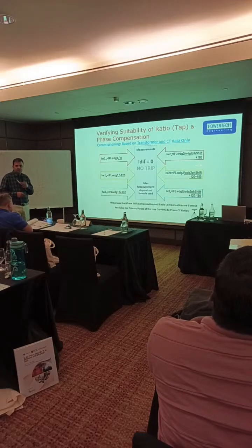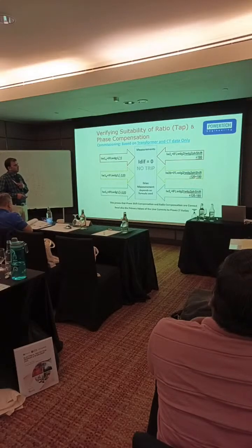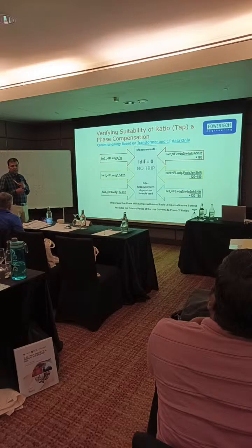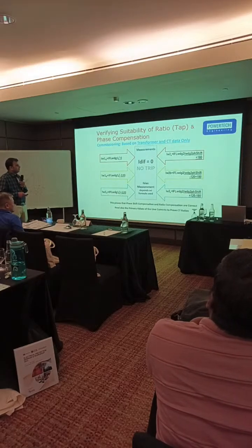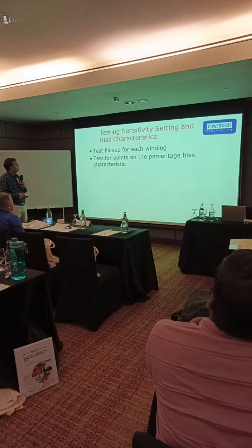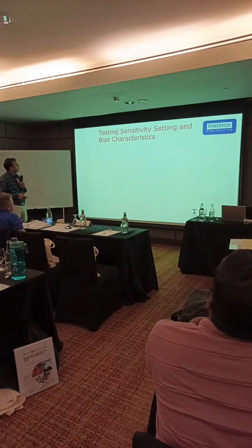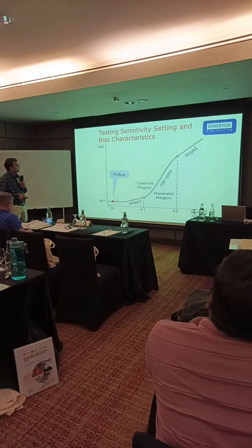If it is a star connection, fine; if anything different, if it is a YD1 or YD11, or DY11, then based on that we have to set this balance current. This we already learned.